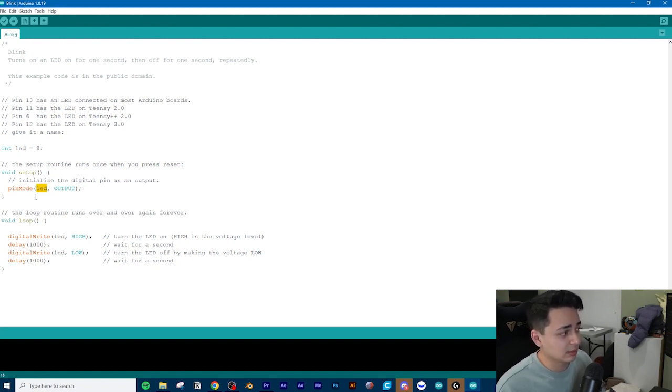So we're saying pinMode is occurring on whatever port was on this variable. We've defined this variable up here to be 8. So we're saying pinMode on port 8, comma. And then in all caps, we're telling the Arduino whether what's going on is an input or output. We said it's an output, and then you end it with a close parenthesis, and then a semicolon.